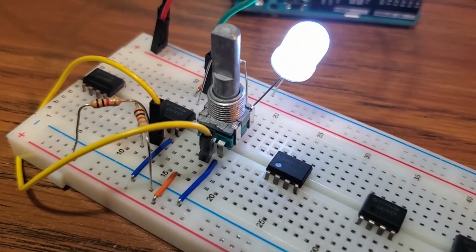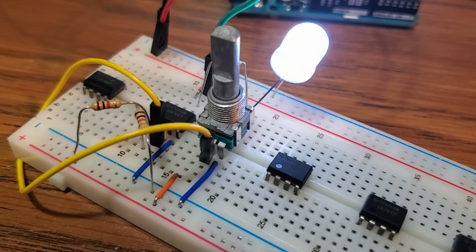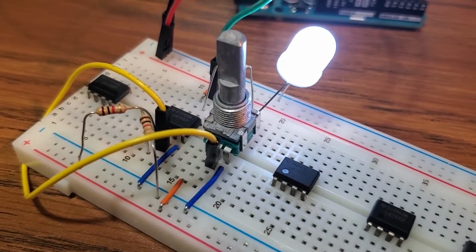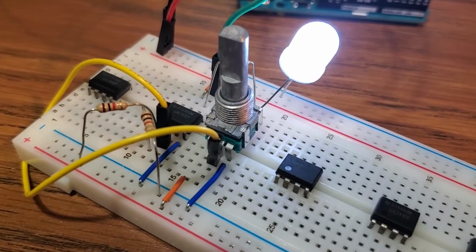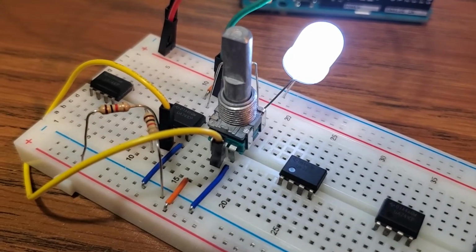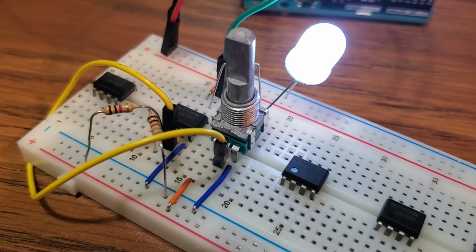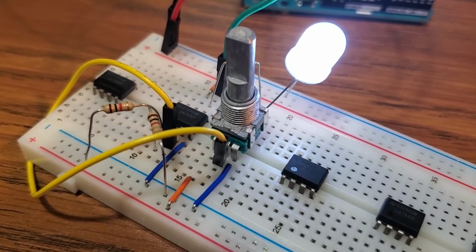The reason why it's more of a digital change rather than an analog one is because the LED has a required minimum forward voltage for it to conduct, and as soon as the op amp reaches that threshold, it will immediately conduct, turning the light on.